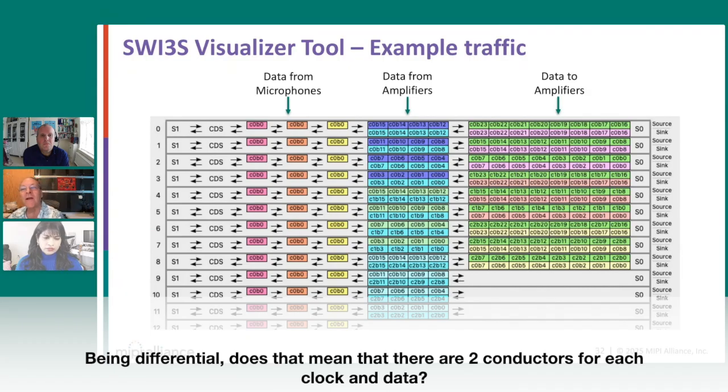That is where the manager drives a 0 on the bus. Then the very next bit, over on the far left, is S1, a rising edge. So every row, there is a rising edge that comes from the manager, and there are requirements in the specification about the jitter. That is the clock. So each row, there's a clock edge, and there you go. So there is only one pair of wires for both clock and data.